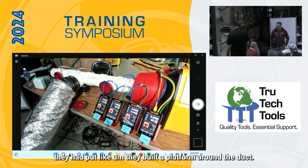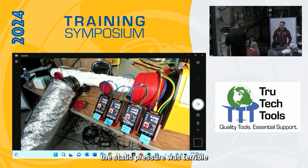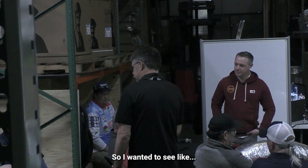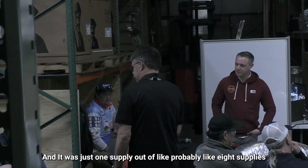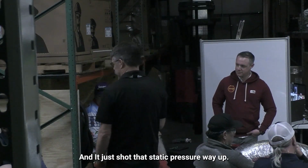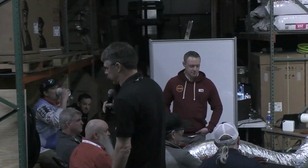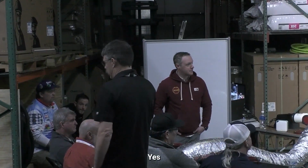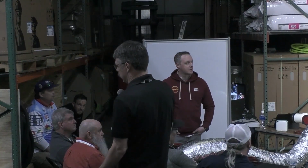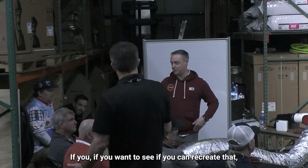Built a platform around the duct and squeezed it down. So just that one supply out of 8 really shot the whole static pressure up, on a maybe marginally sized duct system to start with, and then somebody kinked the one duct and it changed the whole system, right?